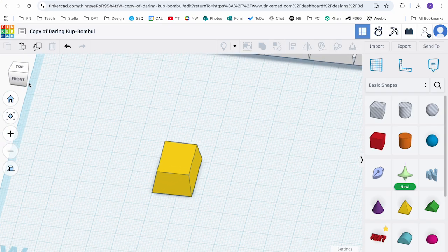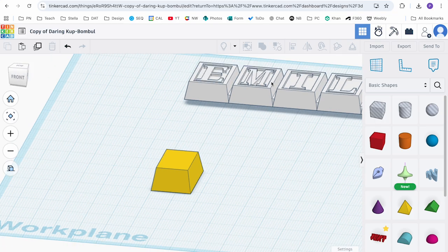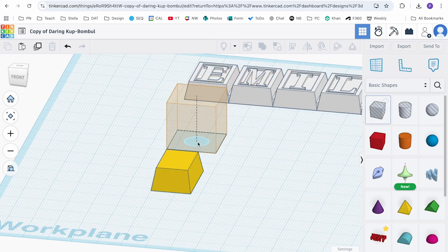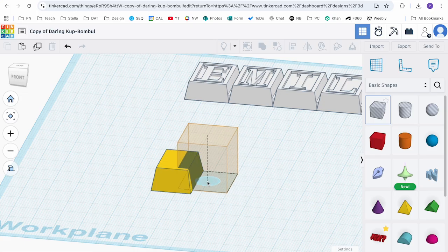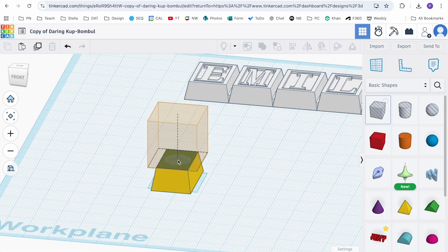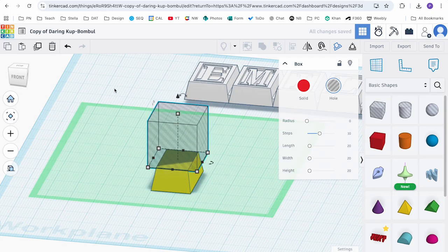So if you look at our chocolate bar in the top right corner there, you'll notice that there's a rectangular recess in the top of the block. So how we achieve that is in a similar way. We're going to grab the cut box, bring it over. Can you see how it's sitting on the work plane? But when I come up to my shape, it will go, oh, do you want to put it there? No, I want to put it on the top. It's now sitting on the top. We can drop that there.